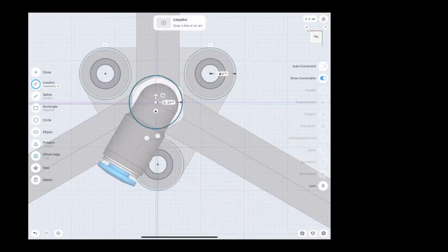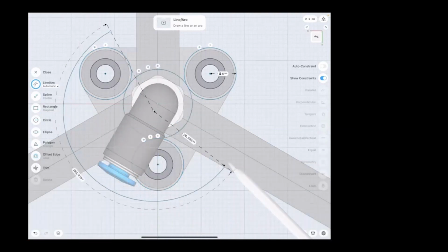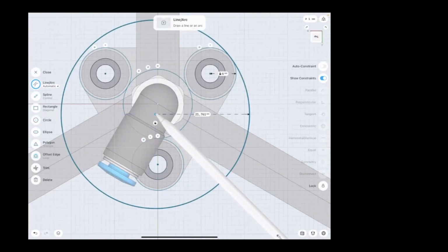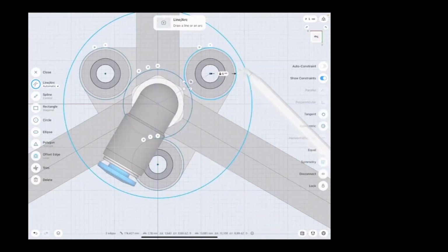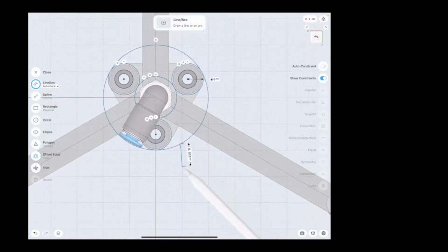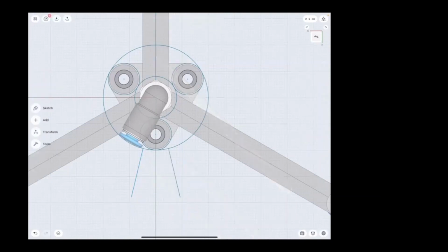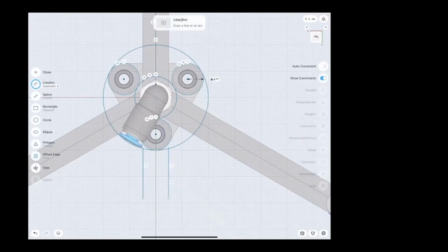Then I will need a 4th circle, to make sure that I will have enough clearance in the workspace between the parts. And then I will need a 5th circle to make sure that I will have enough material thickness. I will need to create a small handle shape to this part. So let me just create 2 lines, constrain those to be symmetrical to a vertical edge, constrain them to be vertical by themselves, connect them and define the distance between these 2 lines.